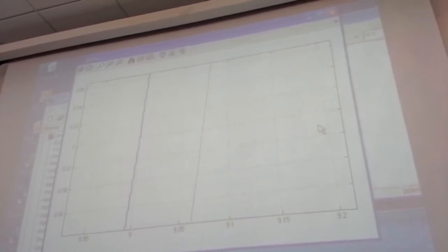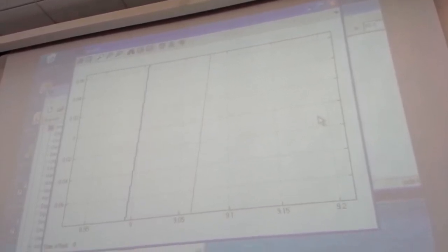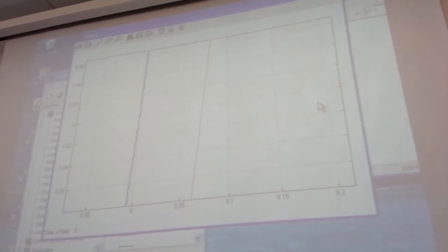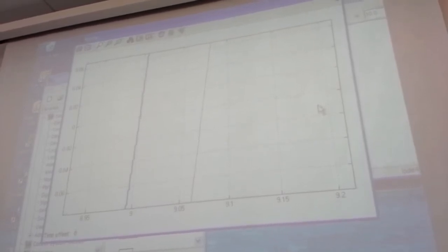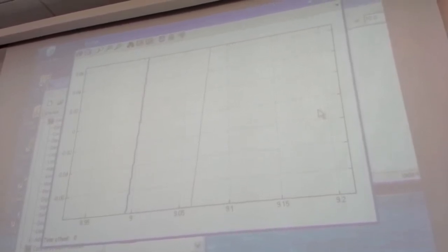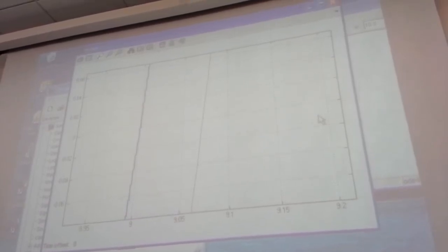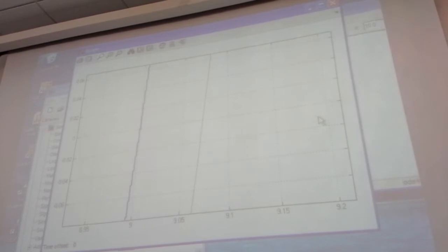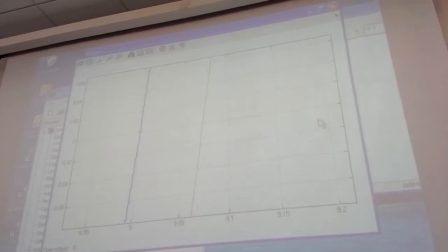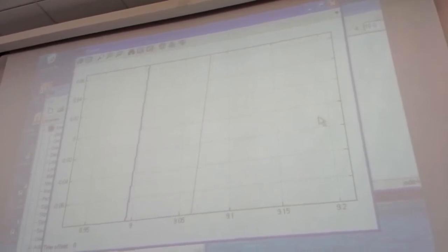Yeah, I guess I was confused on your equal signs. I thought it was a colon. No. Okay. So basically, this is it. That's the input frequency, 2 pi f. If you have time delay TD, that's the phase delay in radian. Remember, not degree.